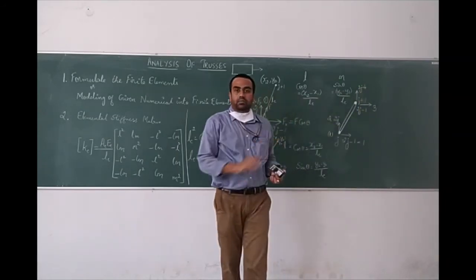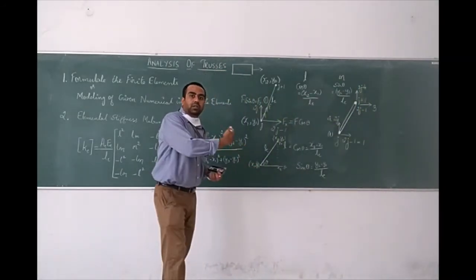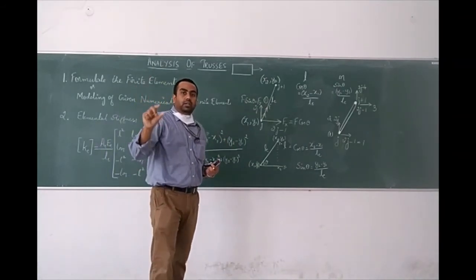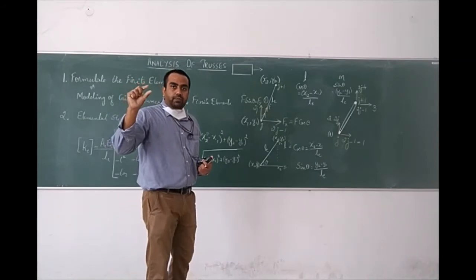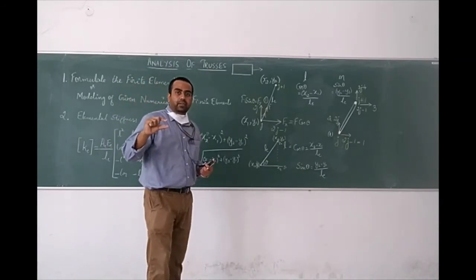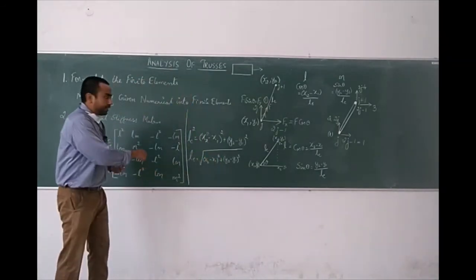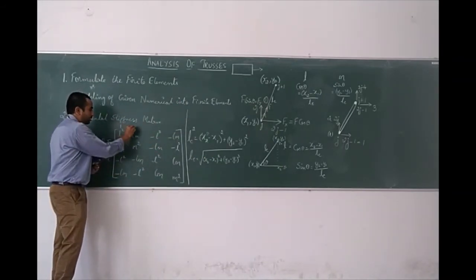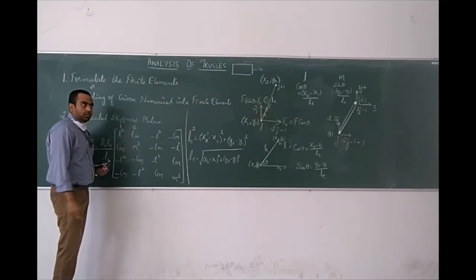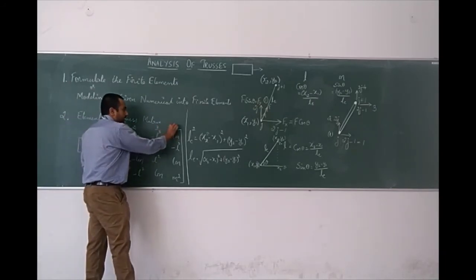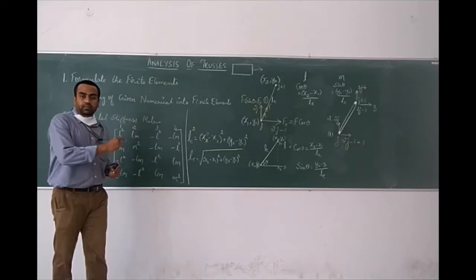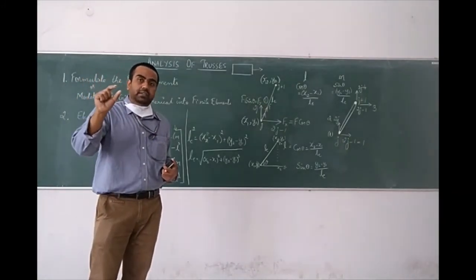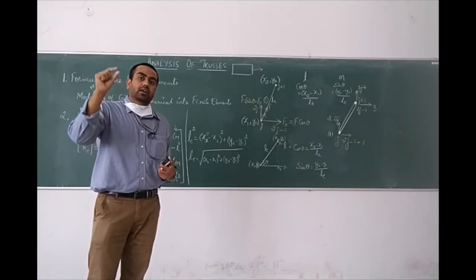So why is it required? When you have to formulate the global stiffness matrix, if you remember the bar problem, the terms that are common, we keep adding them. Here, to mark those degrees of freedom, this is 1, this is 2, 3 and 4. Remember, in bars the number could be considered as the degree of freedom of that particular node itself.